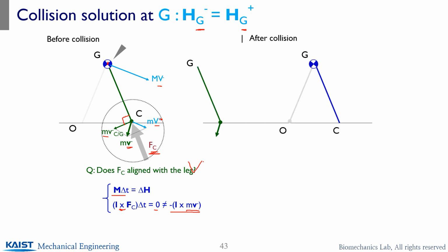Let's assume the before-collision configuration, where the impulsive force at the contact point is applied at some angle with the leg. I don't know the angle for the impulsive forces or their magnitude, and maybe at the other end there are also other forces applied, which we cannot specify at this point because you have mass components. It's not equal and opposite.